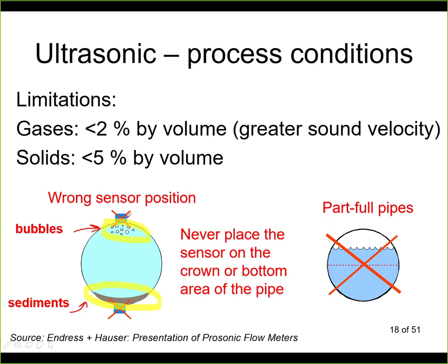Do not install that from the top, because here you may have bubbles, and do not install it from the bottom, because here you may have sediments. So the correct installation is from the sides, left and right, so that the signal is going like this, and eventual bubbles will be up, and eventual sediments will be down.